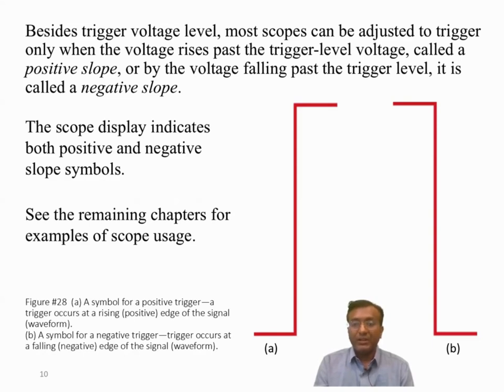Now, in summary, for today's lecture we have seen the understanding of DC coupling, AC coupling, pulse train, and triggering, which allows us to accurately observe and interpret waveforms on an oscilloscope. This knowledge is invaluable in diagnosing complex automotive electrical systems and ensuring accurate readings.